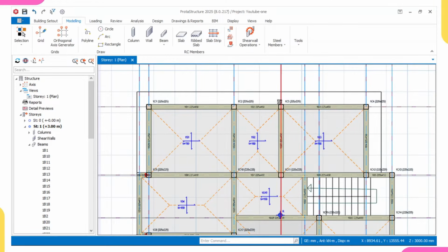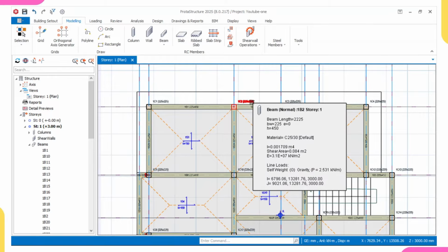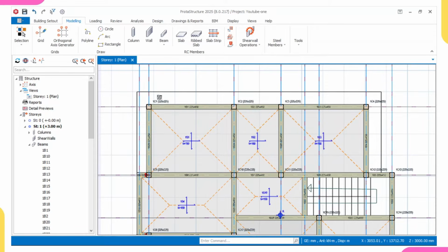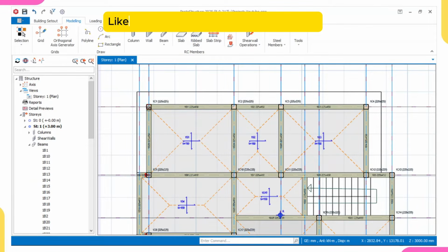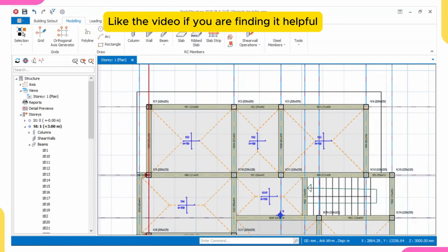If you sum both of them, it will give you 0, because there is a rule that says that the summation of moment at any point will give you 0. I say summation. Moment at any point will not be 0, but the summation of the moment is equal to 0. Then coming to this point now, we are only having one moment at this side. This is not a continuous beam, the beam did not continue from this side, therefore there is no moment here. Since you're having only one moment here, and remember the rule that says summation of moment is equal to 0, that means the moment here is automatically equal to 0.